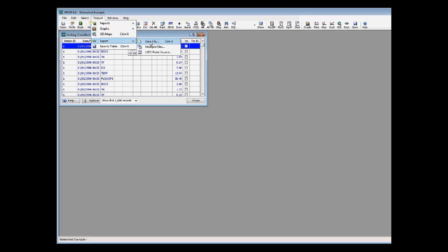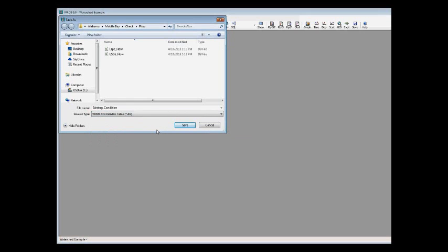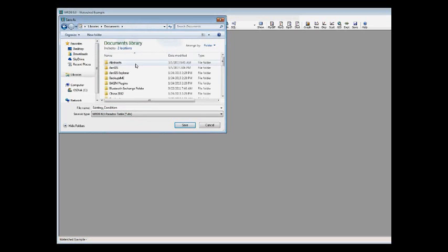And if you go to data file, you have the option of sending this information to a tab separated text file, spreadsheet files, a paradox file, a DBase file, even a WDM file. What we're going to use for WASP is, because the current version of WASP supports paradox tables, we are just going to send it to a paradox file, and I'm going to put it in the same directory where my WASP input file is at, which is over here in WASP.